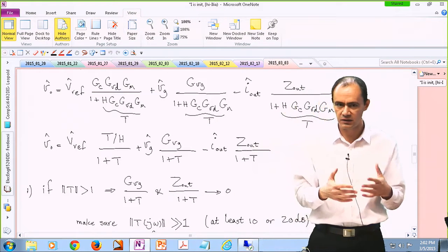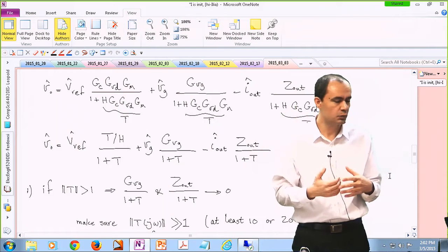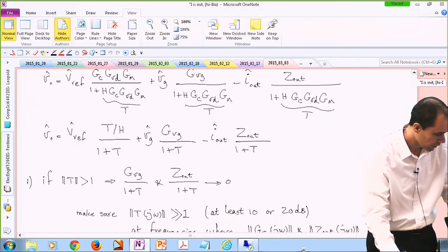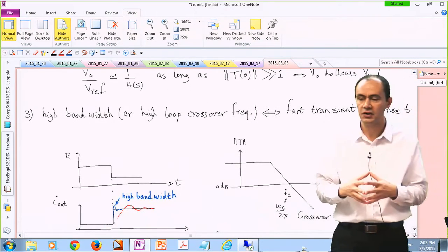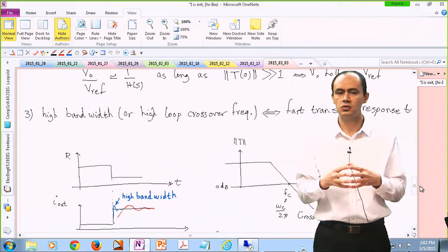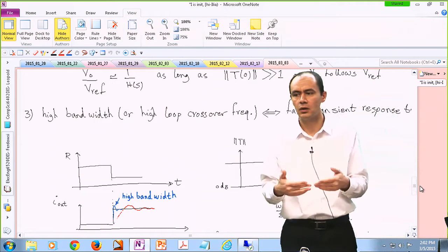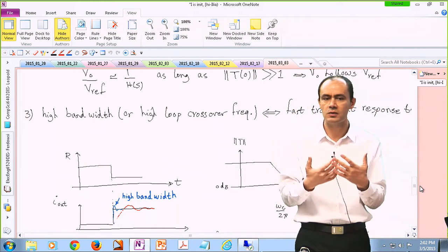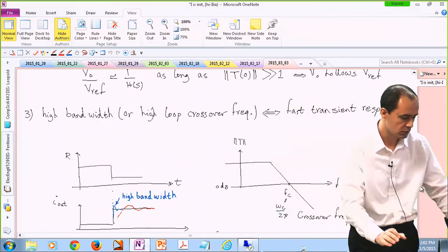So you have a significant 120 hertz harmonic in your input voltage. So you want your loop gain to be large in those frequencies. The other expectation is our loop gain should have a very wide or high bandwidth, meaning that the system should be as fast as it could be. We are always trying to make our system fast in case there is a sudden disturbance appearing in the system. The system can recover itself in a shorter time.